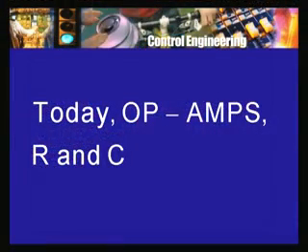Eventually, when the transistor was introduced, and that was in the late 40s, one could even have an electrical network which consisted of some transistors themselves, and such is today's operational amplifier. So, a compensating network may be built up not from just R and C, but from R, C and operational amplifiers. In fact, that is what is very commonly done today. And so, you may have op amps as components, and that opens up a whole new area of compensating network design. You can achieve a large number of transfer functions with the help of op amps and RC elements.